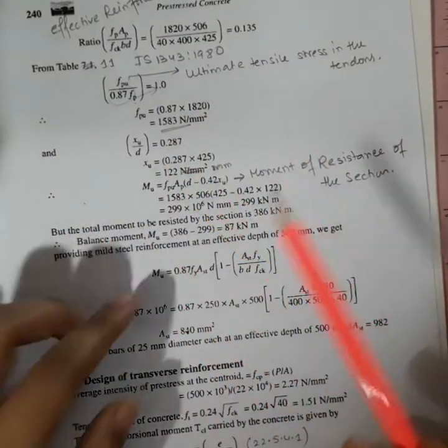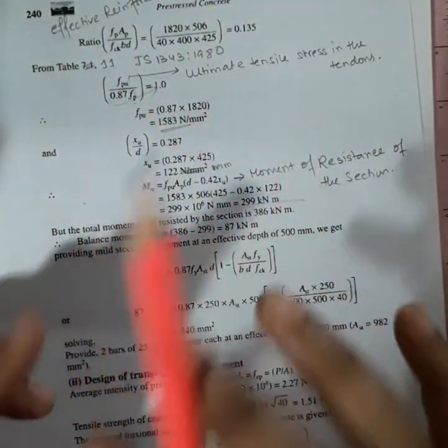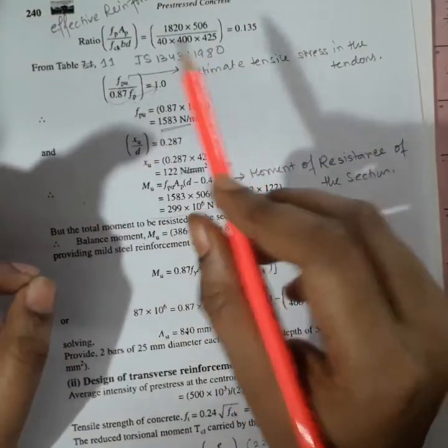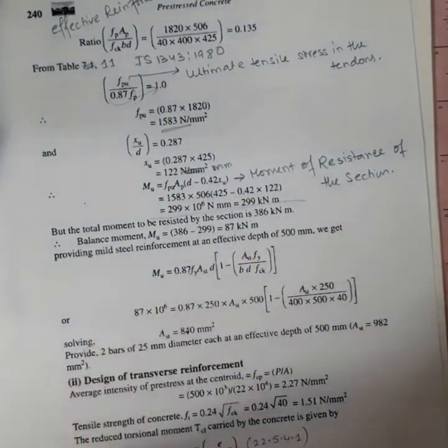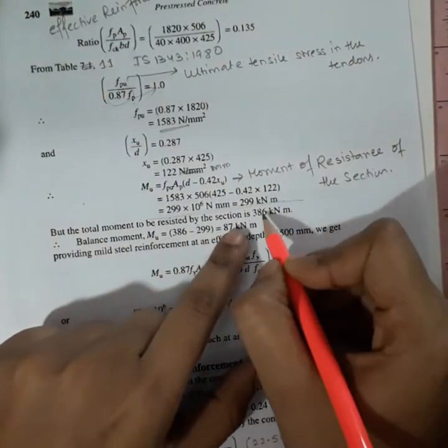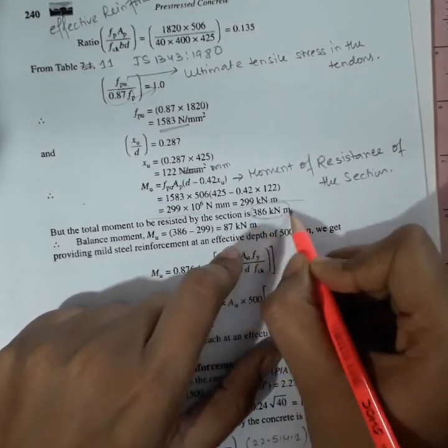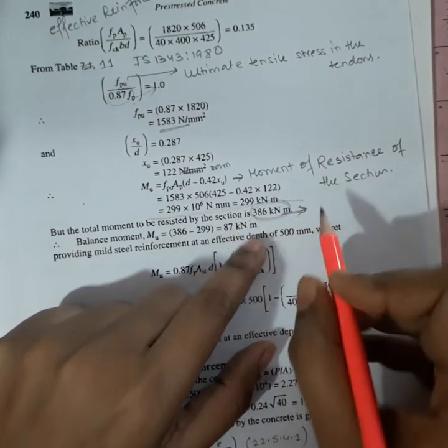So actually up to this, the calculation of moment was only due to the cross sectional area and the effective tensile strength of the steel. We have not considered the torsional effect in this calculation, but by incorporating the torsional moment into account, we have got this moment. So we have to consider this moment to be the final; I mean, by benchmarking this moment we have to design.